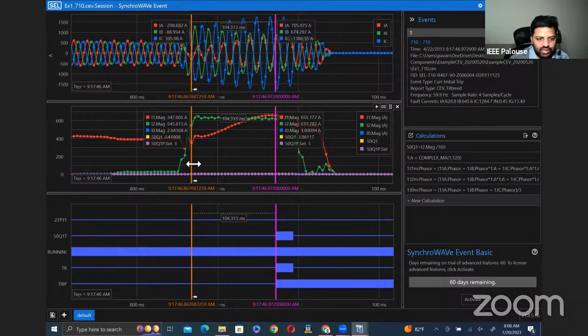So when we have the negative sequence component I2 increased in this case, our 50Q element is actually looking at the negative sequence component. The 50Q1 value, which I calculated here, is our negative sequence component divided by the CT ratio. You get 3.41 here in this scenario, which is crossing our set value of 3. So that's when the timer actually started.